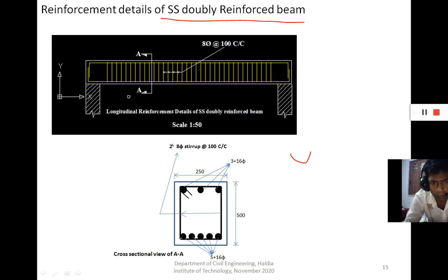So it means the reinforcement should apply at the bottom because tension is developed, and for strengthening the section we apply the steel in the tensile zone and compressive zone. As we design the beam as doubly reinforced, the additional steel is applied in the tensile zone, and in the compression zone also steel is used to increase the strength of the section.